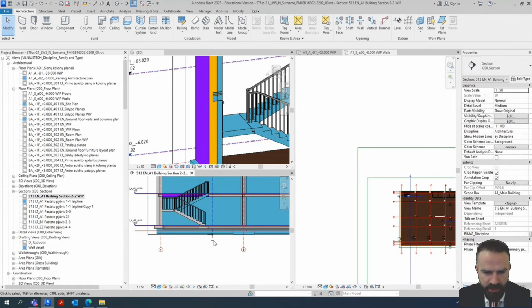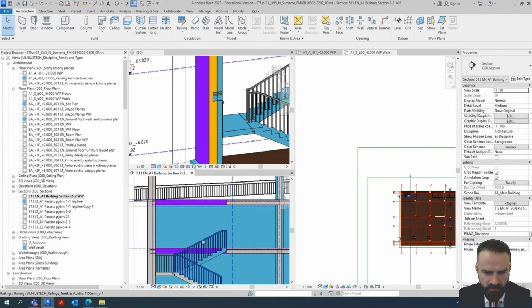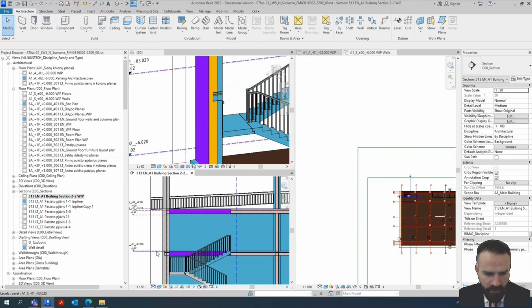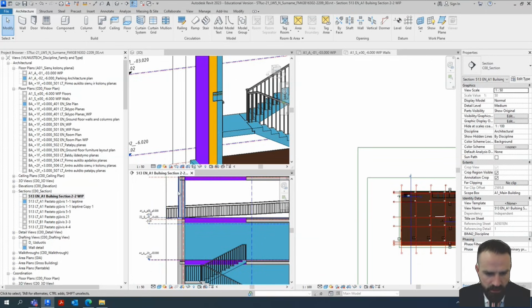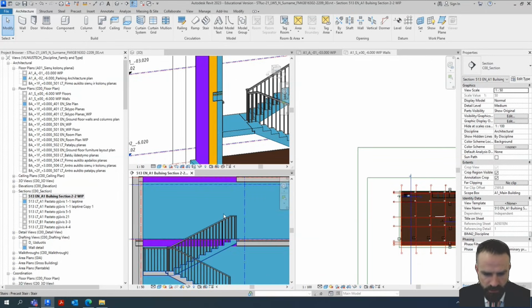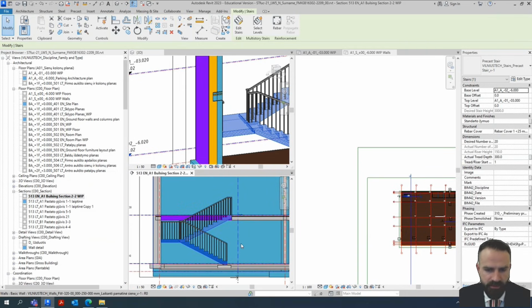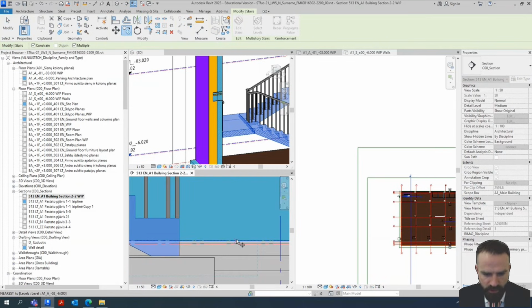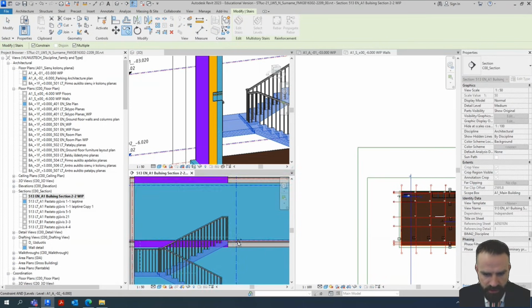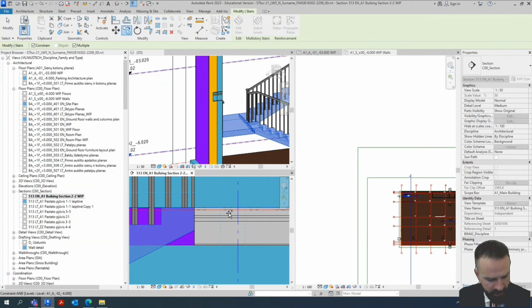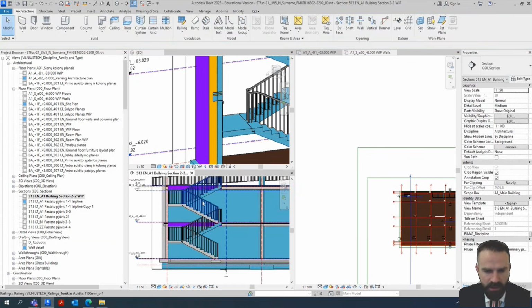Okay, let's create stairs for the other floors. If the height of the floors is the same on all floors, you can copy the stairs from the bottom level to the next level. I use the copy tool and copy from the architecture level to the next level. I click shift and move it perpendicularly up to the next level, and I copy it.